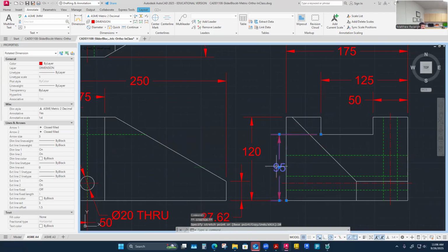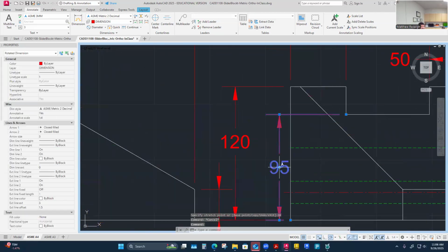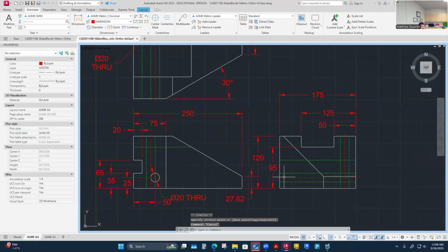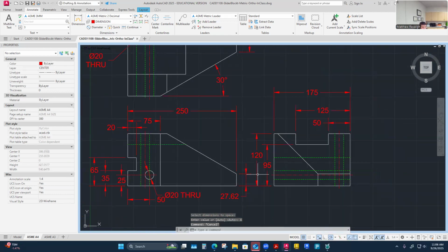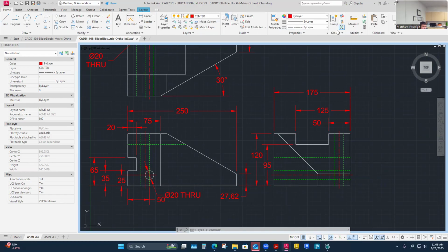So I'm going to start cleaning it up, I think. I feel like in this particular drawing, my 10 millimeter offset is just a little tight, is what I find. So I'm pulling it out just a little bit beyond 10. You could put in another number, but I've also got to work with what space I have. So what I'm doing is some space alignment. I think I'm totally done. 10 millimeter as the first intermediate dimension, and then 6 millimeter thereafter.